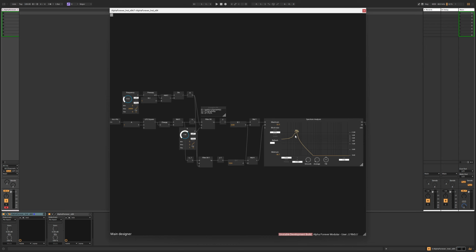And here now you can see both of the filters at the same time, and on low frequencies they kind of match, but when I looked back on the video I saw that on higher frequencies there's a dip in the response curve. I'm going to move this frequency knob and raise the frequency, and then you will see that the orange line is going to dip, and there's a blue line below that which is going to go straight, and the blue is the correct one, the orange is the wrong one.